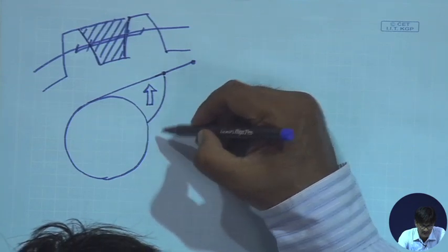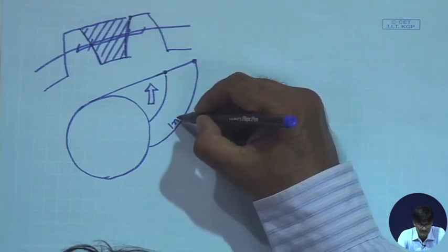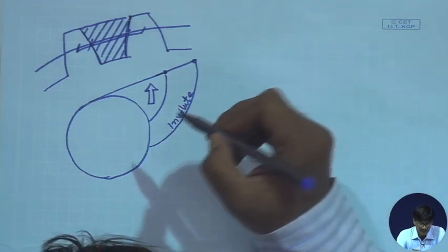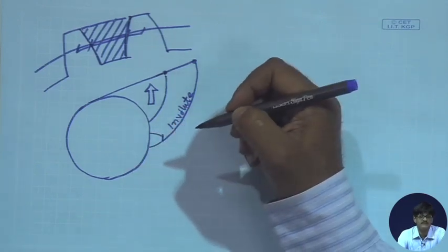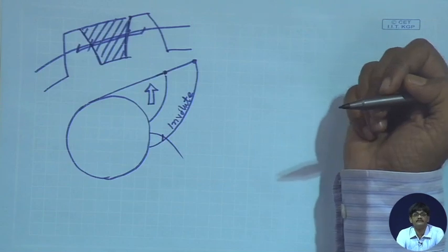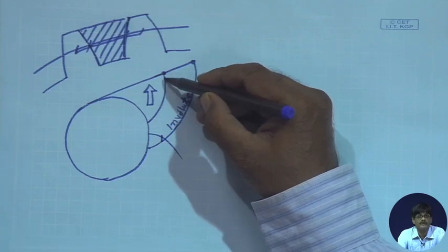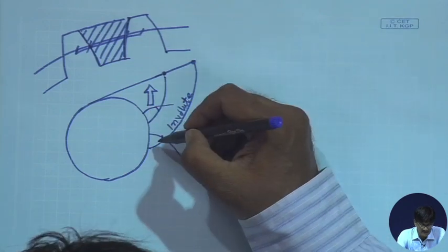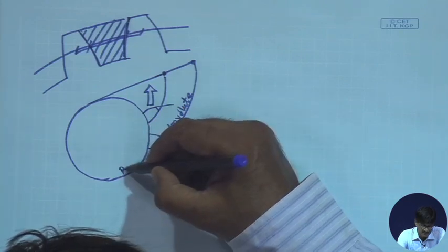describes an involute. There are a lot of interesting properties of these curves, but what we are concerned with is that every gear tooth is essentially part of these involutes, an involute on this side and an involute on that side, and part of it we adopt as our gear tooth. This one is another involute, another gear tooth perhaps. What does this involute depend upon? It definitely depends upon the radius of the circle. This circle is called the base circle.